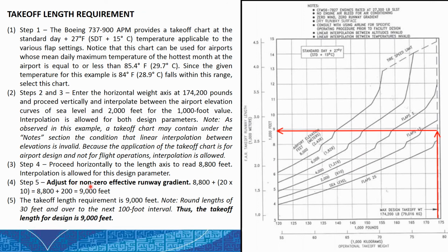So because we have non-zero effective runway gradient, we have to make an adjustment in the takeoff length requirement. So here, 8,800 plus 20 multiplied by 10, and we get 9,000 feet. So the takeoff length for design is 9,000 feet.